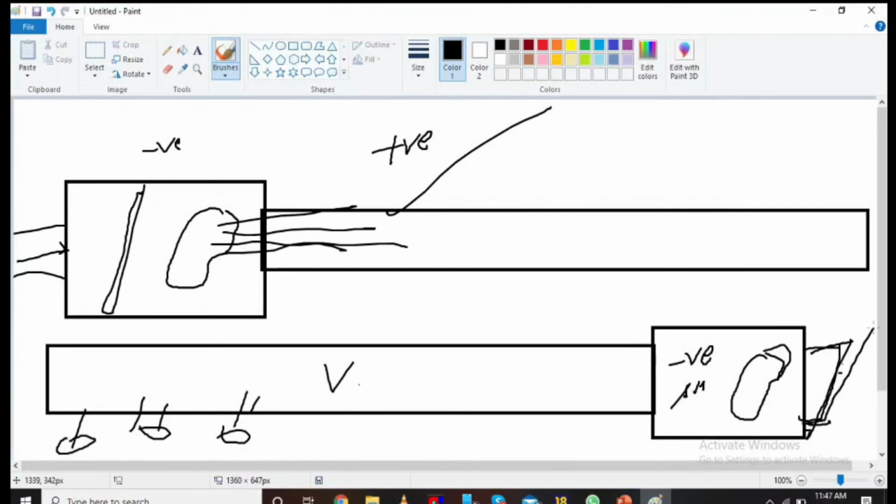The outlet will look something like this. Through the outlet it is going to push the air like this. So positive static will be very less. For exhaust system fans, negative static will be more, positive will be less. For air conditioning supply fans, positive static will be more, negative static pressure will be very less, because it is not needed. For now just keep in mind, during external static pressure calculation, that is the capacity of the fan, how to arrive at the capacity.